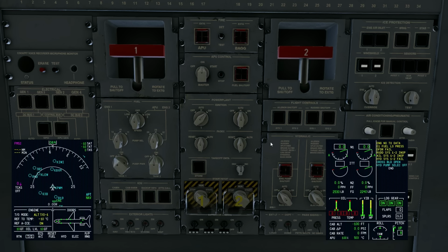That's totally normal right now, because the way it works is after an engine starts, the computer goes to work. So the computer starts comparing parameters, and after a couple minutes, it's going to return a solution. If the temperature it detects is within limits, and the pressures are right, and the anti-ice solution makes sense to the engine, it's going to go ahead and accept the data. You know the data accepts because of two indications, or I guess three. This will all go blue, meaning it's good.